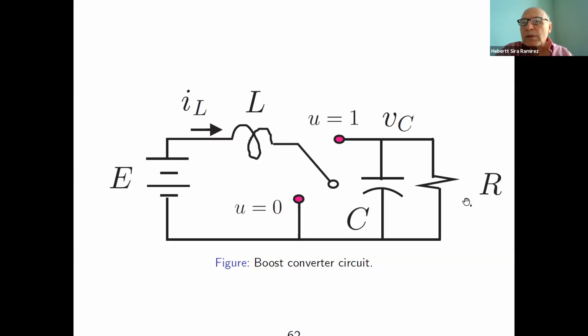And that's one type of disturbance in the dimension of the voltage variable. You might have other disturbances affecting your source. Your source might be the result of a rectification of an alternating current, so your source is not constant. Your source is slightly fluctuating in a periodic manner. That can be modeled as an additional voltage source acting in conjunction with the battery, but alternating with a small amplitude.